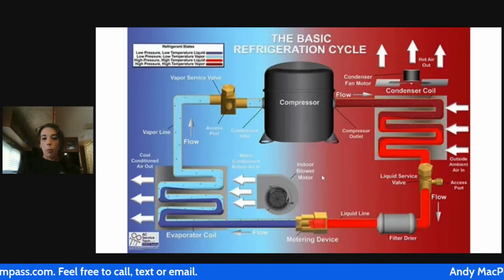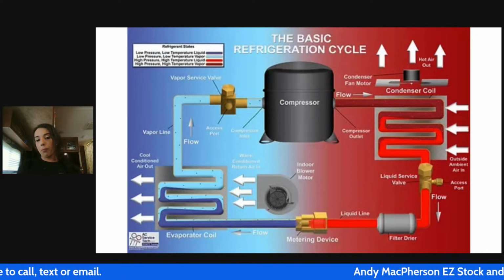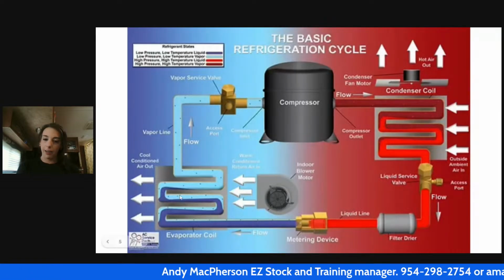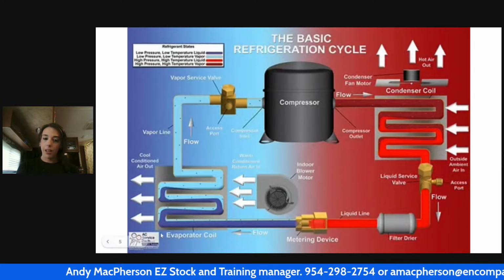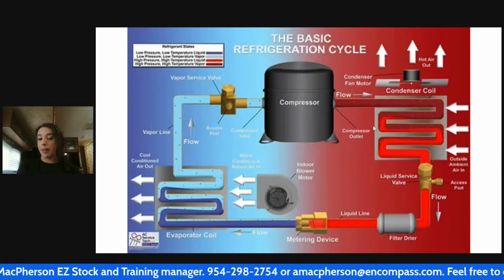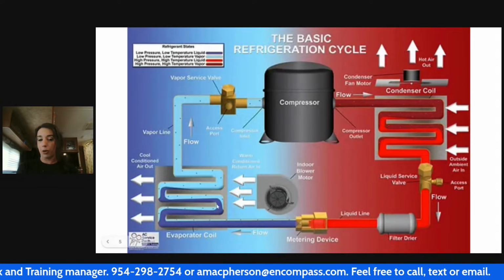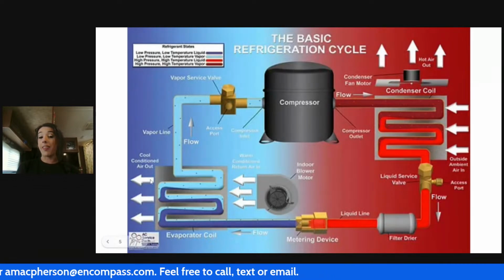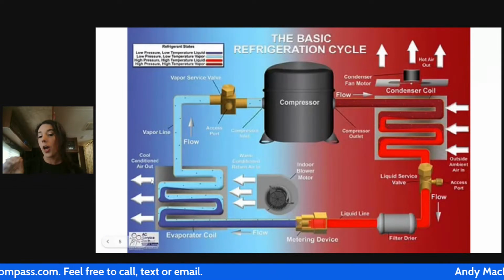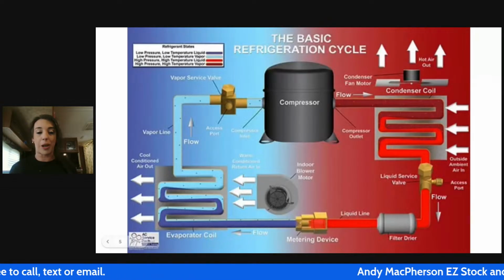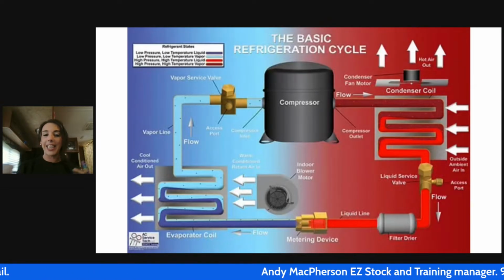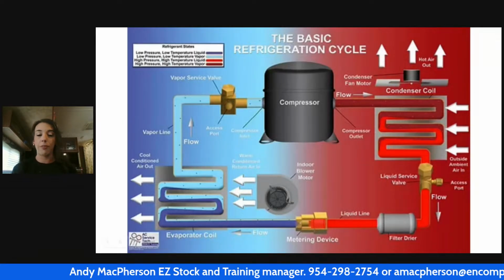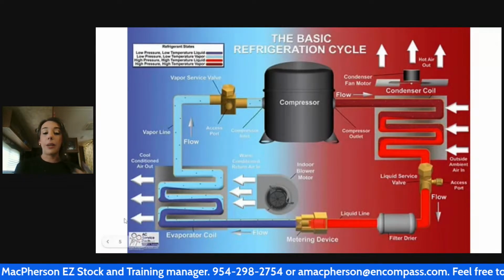Okay, so if we're taking air out of the room that is 85 degrees, this blower is blasting it past this evaporator coil, right? That evaporator coil is removing the heat from that air and sending it again through the cycle. Once it is out of the room and across that coil, it's not our problem anymore. Now we're blowing in that same air. Remember this, we're not gathering new cold air from somewhere and blowing it into the room. We are taking that same air we removed the heat from, and then we're blowing it back into the room via the supply. So that's really important, guys.